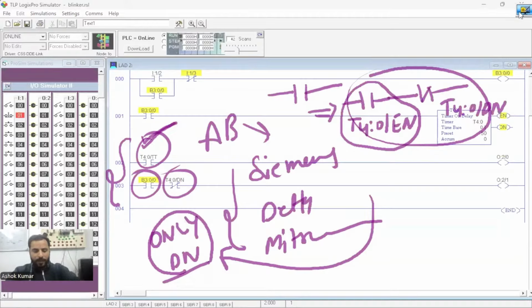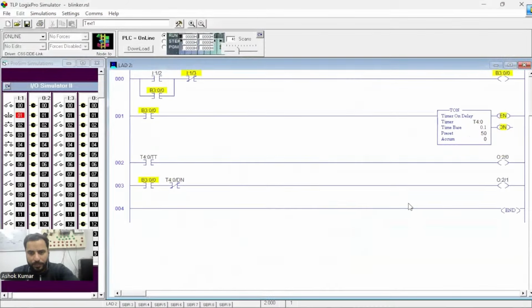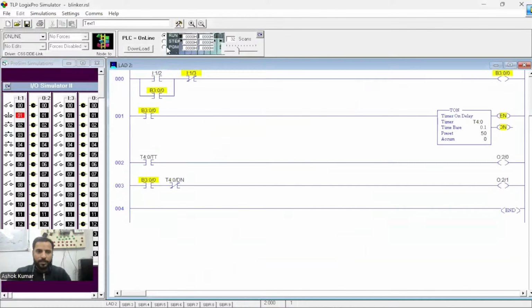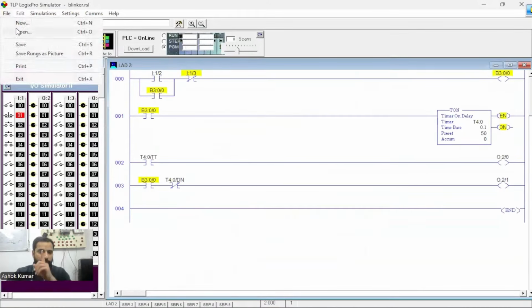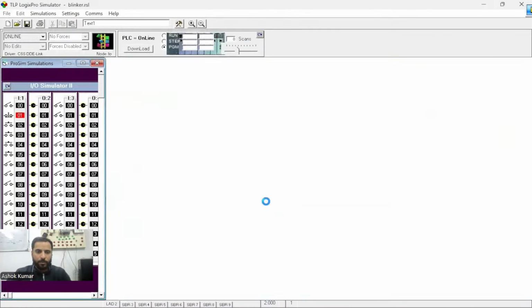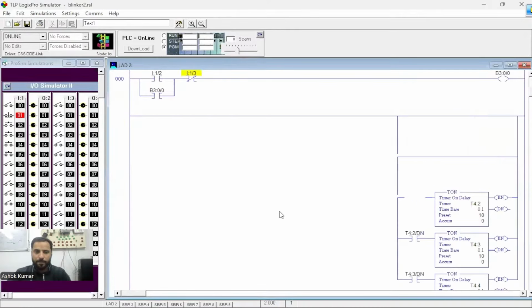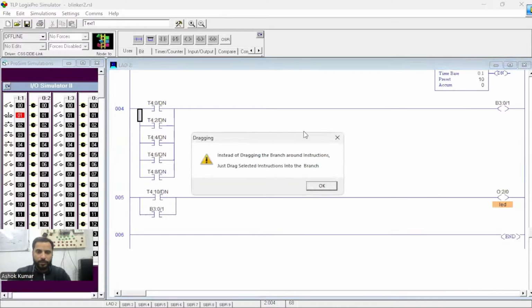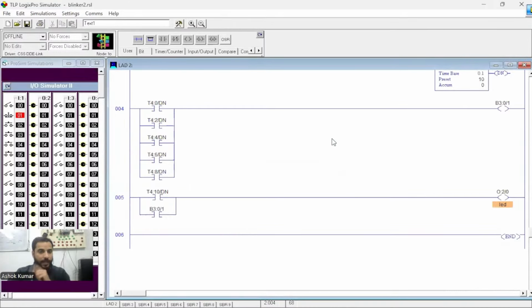Okay. Because I already told you once we complete the concepts of Allen-Bradley, it won't take much time to understand the concepts with the Siemens, right? I hope it is clear what is the solution for enable TT, right? Now let's come back to that question, because right now we understood this with only one timer. Now when we have the scenario of solving multiple problems, this was the problem which we just did, 6 times on, 6 times off, but we have to solve it with the done bit without using TT, without using enable, right? So how can we get the solution for this without using TT and enable?